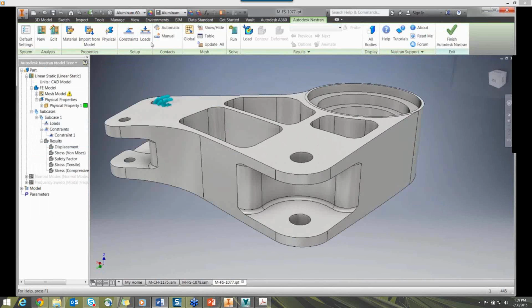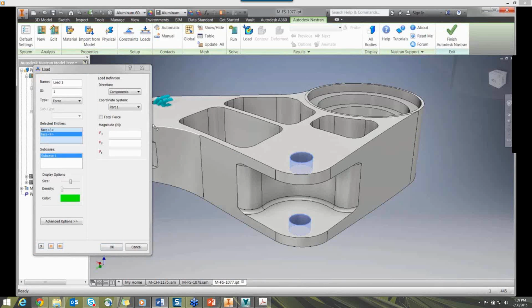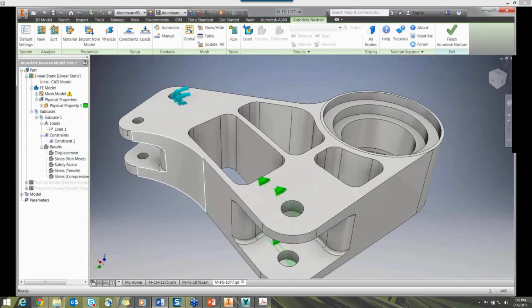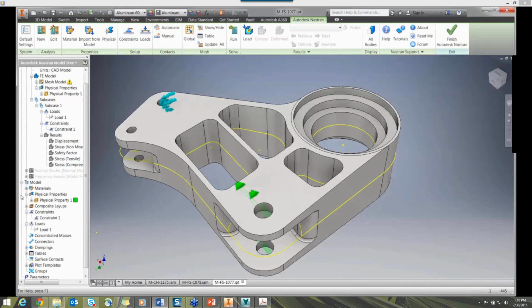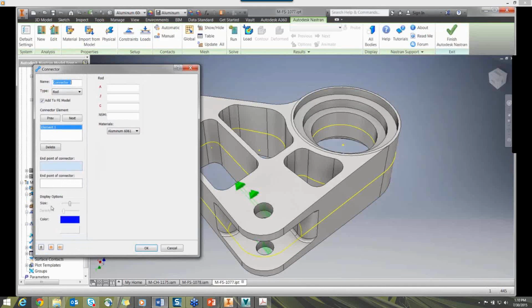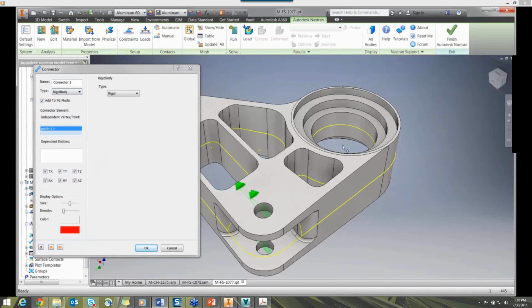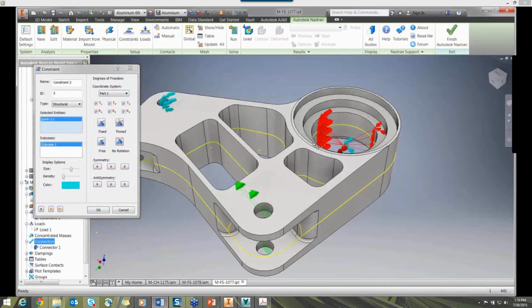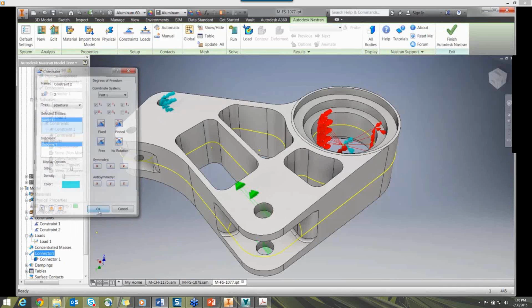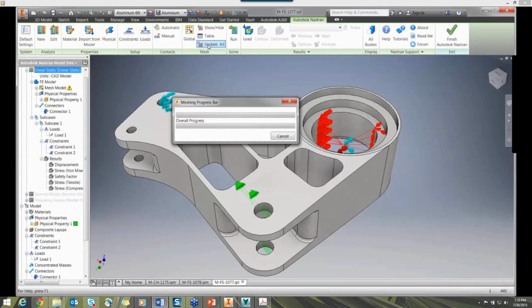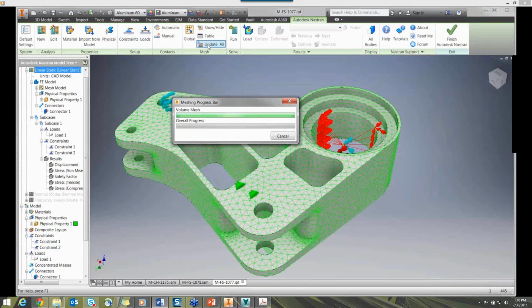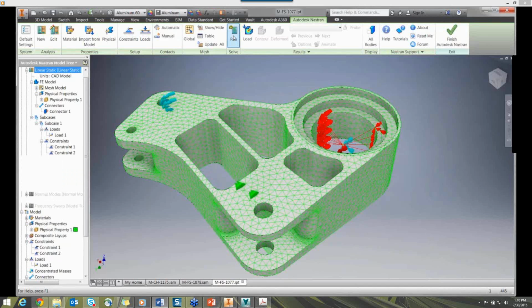So we're adding some constraints. We want to add a load as it is in the suspension assembly, with the load from the push rod through these two holes here with a load of 5,000 newtons. Next, we are able to constrain using some special case constraints. In this case, it is a revolute joint that acts on that interface there. We release the rotation, indicating to the solver that this part is free to rotate about that axis.